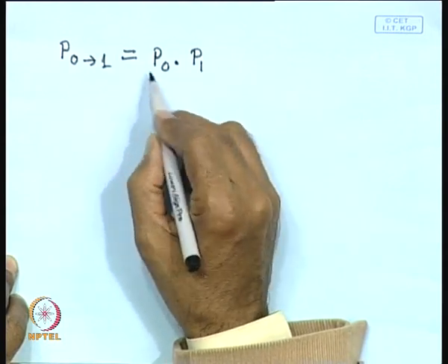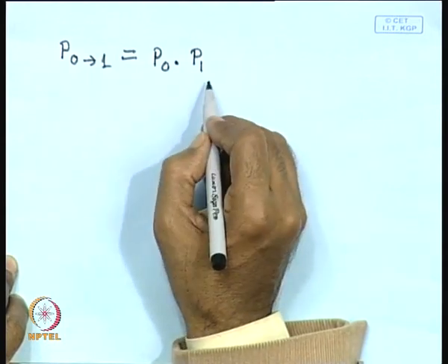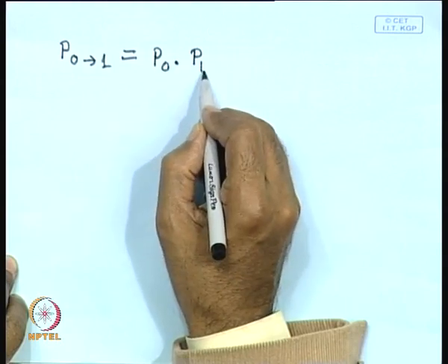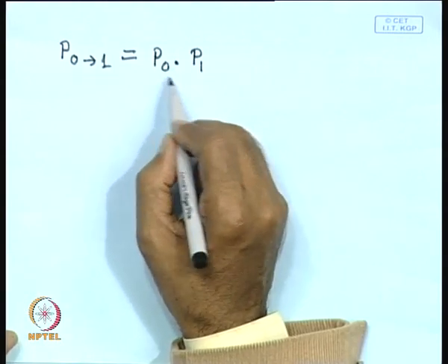From this you can find the switching activity in static CMOS circuits, and we have discussed in detail how this can be calculated in different situations and for different types of gates: NAND, NOR, exclusive OR and so on.